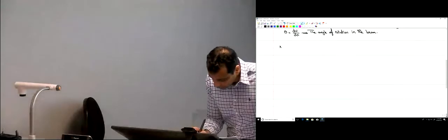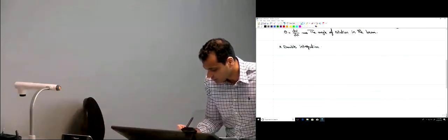So now, how can we find the deflection at any point due to a given load, or the rotation at any point due to a given load? We just wrote that this is the equation that we have. How are we going to use this equation to find v, or theta? Simply, here we have a method called the double integration method.